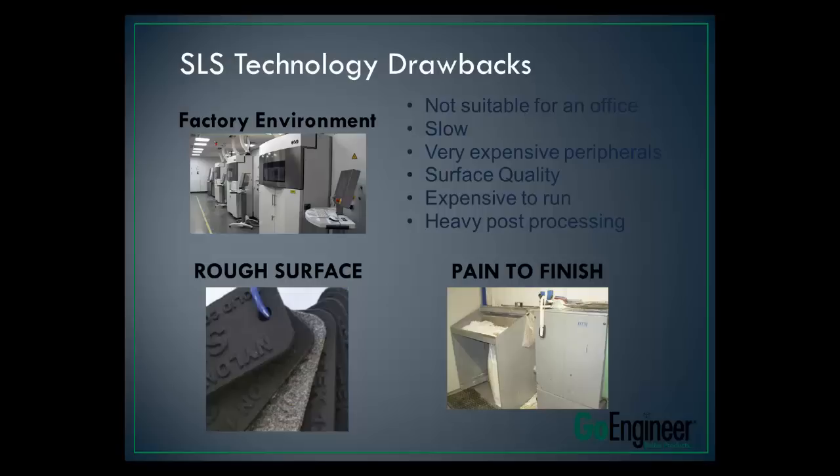The other crazy thing about this machine is how long it takes to warm up and cool down. To warm up, it can take up to 2 hours. So let's say you have that dedicated operator, you're paying them basically 2 hours to sweep the floors while the machine warms up before you can even run parts. And another thing is the cooling down system.